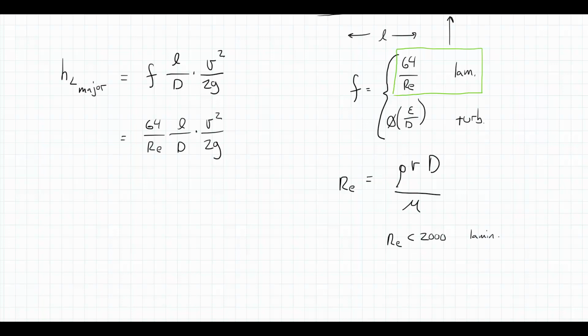And again, since we are using this Moody friction factor f of 64 over Reynolds, we have already assumed laminar flow. So we might need to check this if we have a case where we're not sure, is the flow going to be laminar or not? Well, first, let's calculate the Reynolds number, make sure it is laminar, then we can go and calculate our equivalent resistance based on that laminar flow.